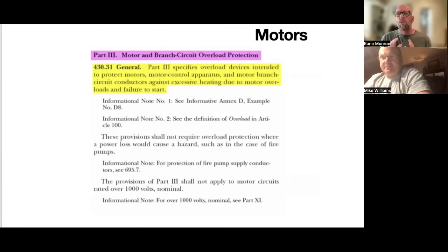Okay. Overloads, just remember, overcurrent is a quick situation. It's a ground fault situation. So it's quick. It's your breaker that's tripping, or your fuse that trips. Your overload, and I believe that's step number 2 in the flow chart that I had there, it's a slow trip is what it is.